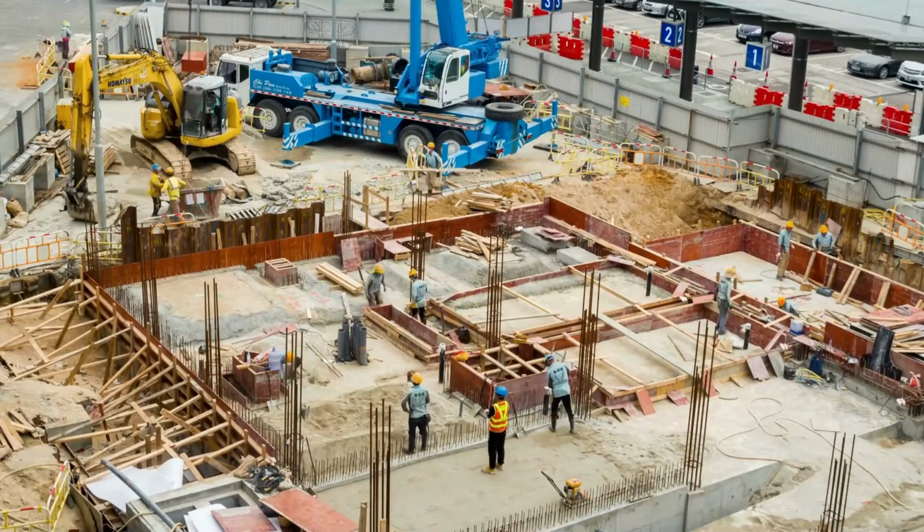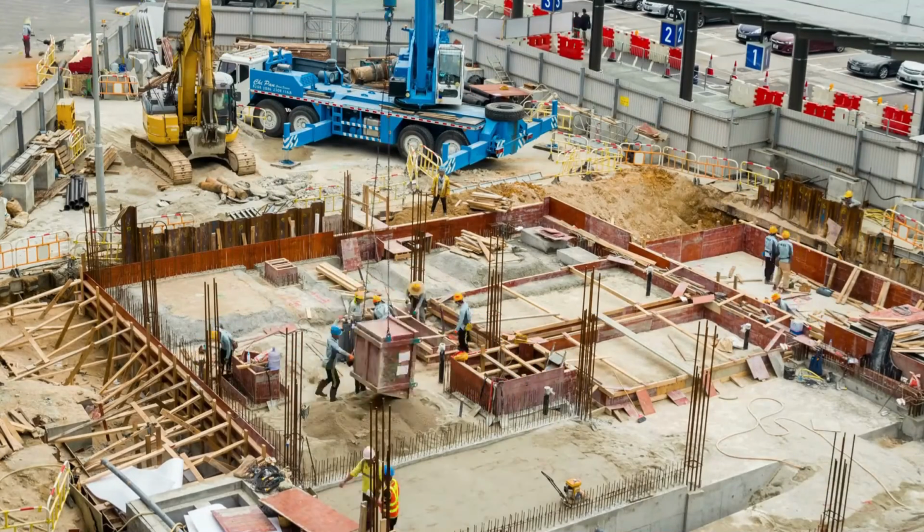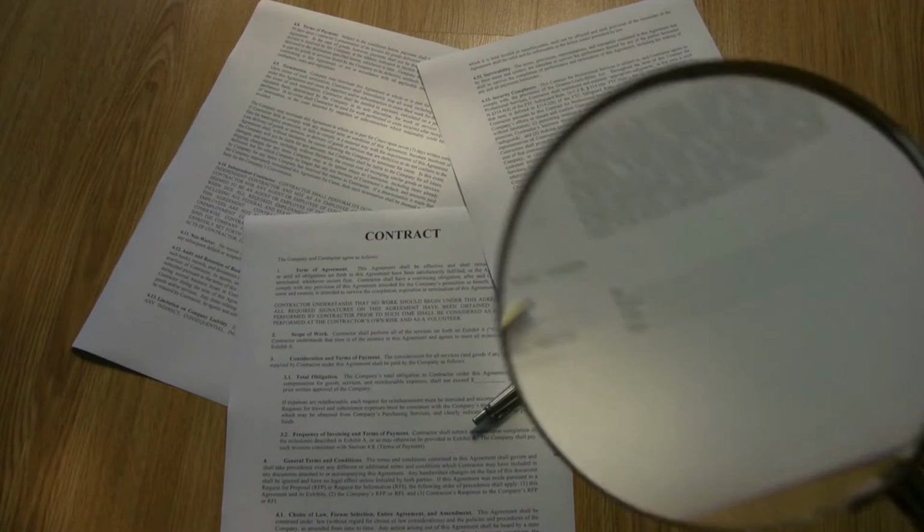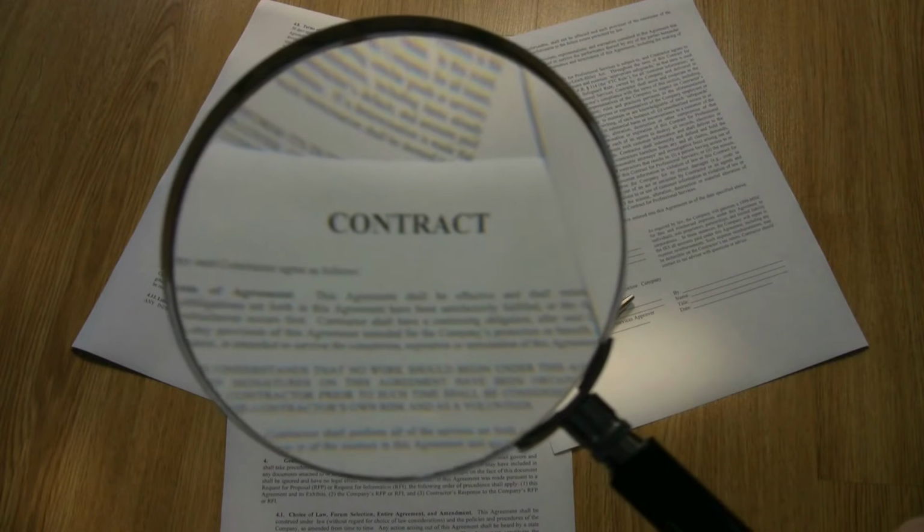Now, subcontracting is where we engage subcontractors and suppliers to do work on our behalf. For these tasks, because we've engaged the subcontractor to complete a scope within a fixed time frame, we can look at the contract durations and the timelines we've agreed with them. Now, contracts might not be specific enough. We might be developing a schedule at a time before we have subcontractors. In that case, we just need to engage with our supply chain and understand how long it's going to take them to complete the works, and then work out if this matches our requirements for the project.